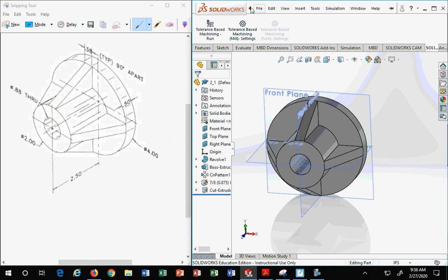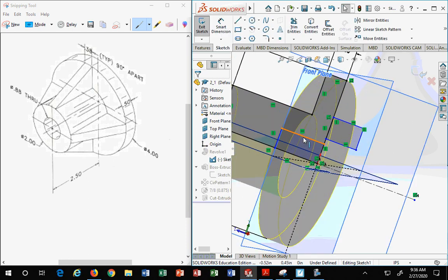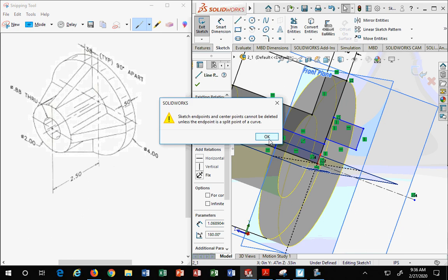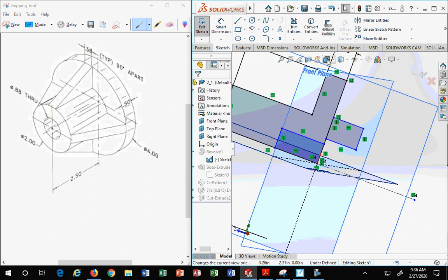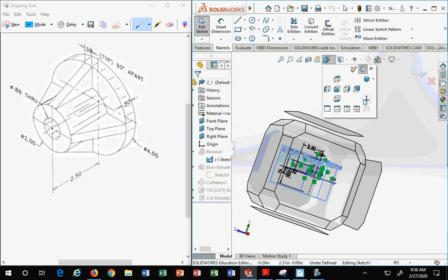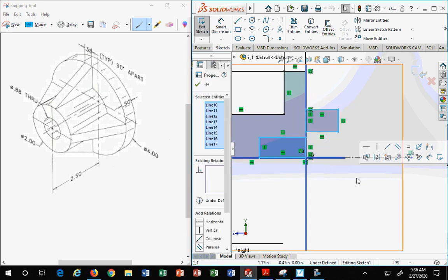When you want to create a detailed drawing, the things that you have to do, one, what did I say in the beginning? Make sure you have your dimensions. If you don't have any dimensions in your base geometry, this is the one where I left a bunch of junk on there just to mess with everything. If you do not have dimensions in your base geometry, you will not have any dimensions in your detailed drawing to work with.